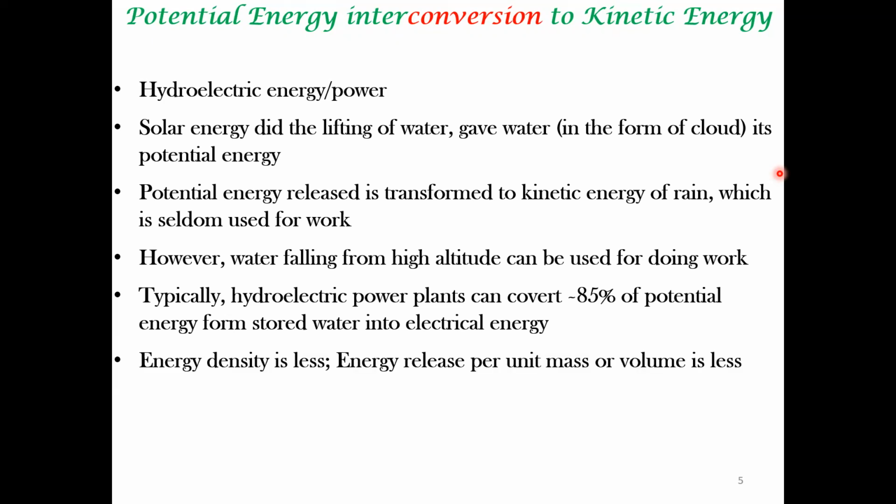So energy density, however, in a hydroelectric system is very less. Okay, so the energy release per unit mass or volume is very less. That's the main disadvantage. Even though the energy conversion efficiency is fairly high compared to other forms of energy, the energy density is very low. So that is the disadvantage. So we'll be looking at these kinds of trade-offs often in this course as we go along, because from the early days of thermodynamics, historically, if you see the history of thermodynamics, this notion of which form of energy is better and in what way it is better.